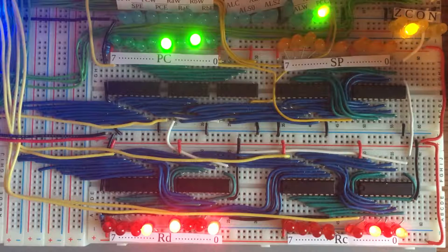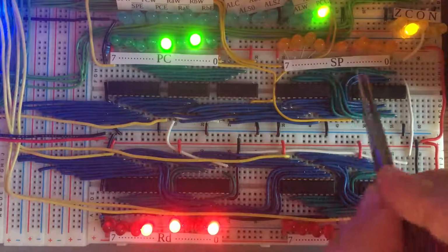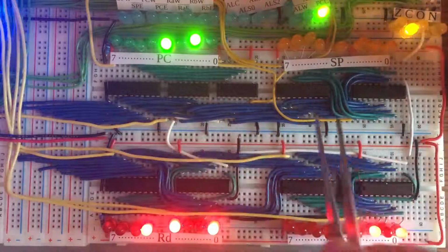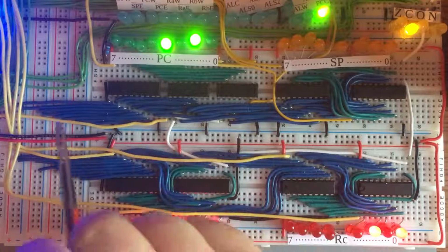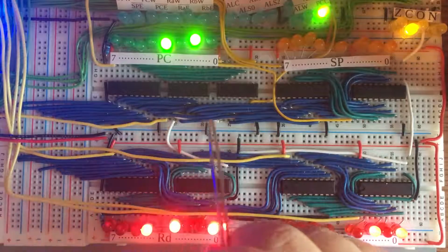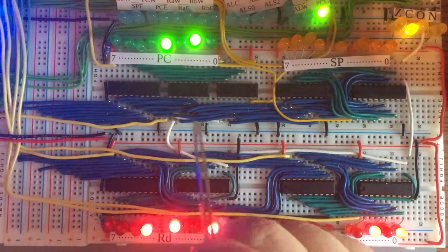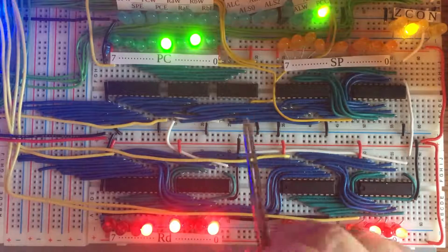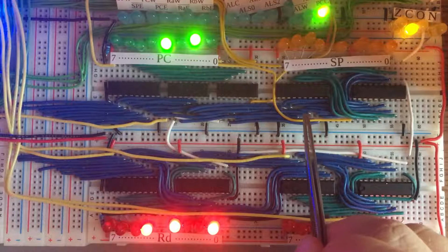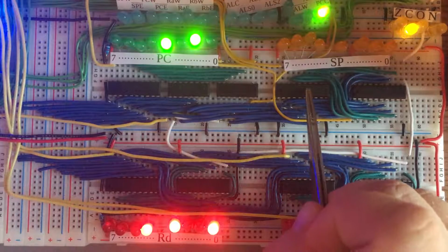And one of the reasons I did that is because I decided pretty early on that we're going to need more than Ben's 2 registers. And in fact, we have 6 program addressable registers. We have the stack pointer up here, which works in exactly the same way. So it too is connected to the bus along these blue wires. So on the way, the program counter is obviously interested in what's on the bus as well, but we'll ignore that for now. And so we get to the stack pointer here, and so that too has a buffer.